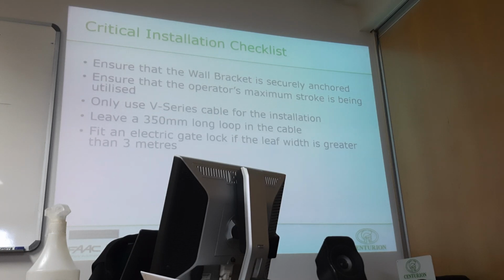I'll show you now how we're doing it. When I press this button for this motor to open, it will actually unlock this lock. I'm doing it wirelessly, but you can do it hardwired or wirelessly. You'll hear it: the moment I press the button, you can hear this one click, and then it will open the gate. The controller will tell the lock to open just before the gate physically starts moving. So try not to have a manual lock with a chain, because you're going to forget it, and eventually there are going to be some issues.